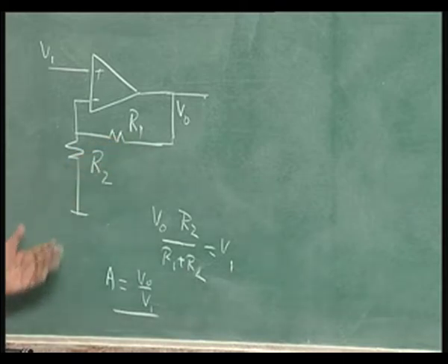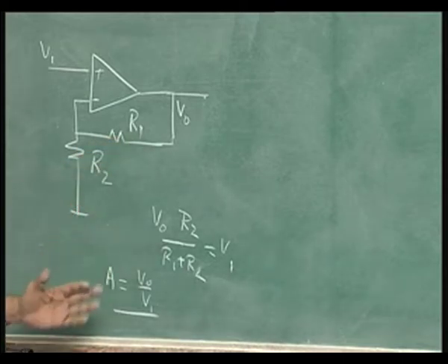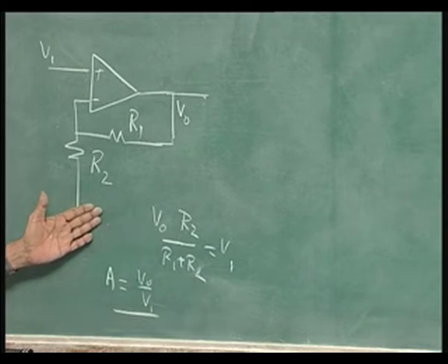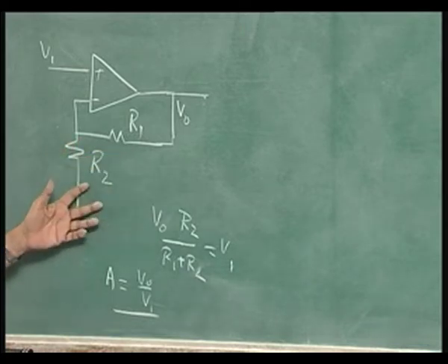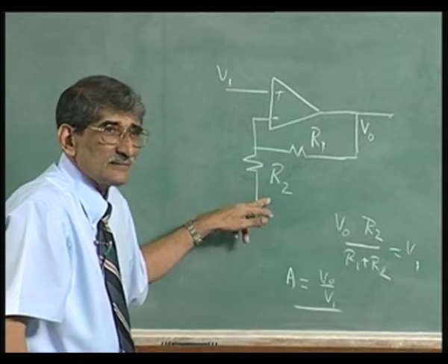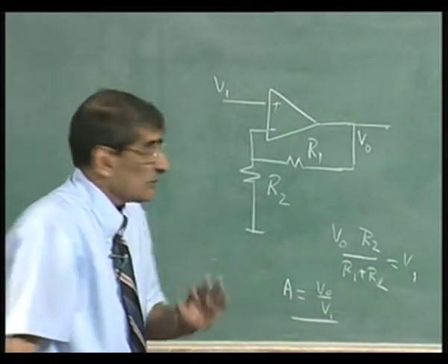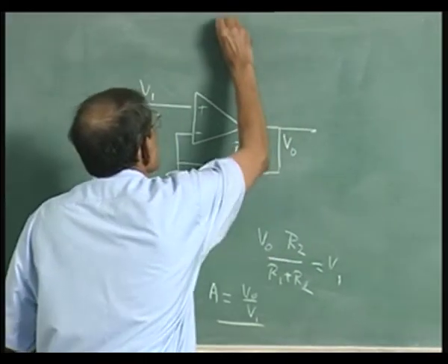1 plus R1 by R2, I think you have been tired of listening to this probably. 1 plus R1 by R2 is 3. That means R1 by R2 is equal to 2. You make these 2 compared to that, that is 3. And then what do you have? Wien-Bridge.